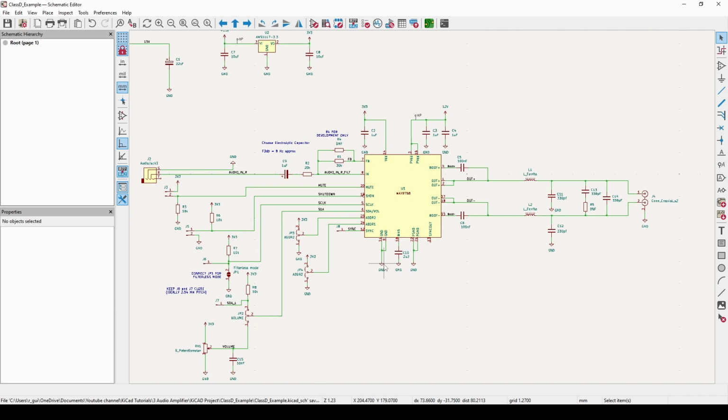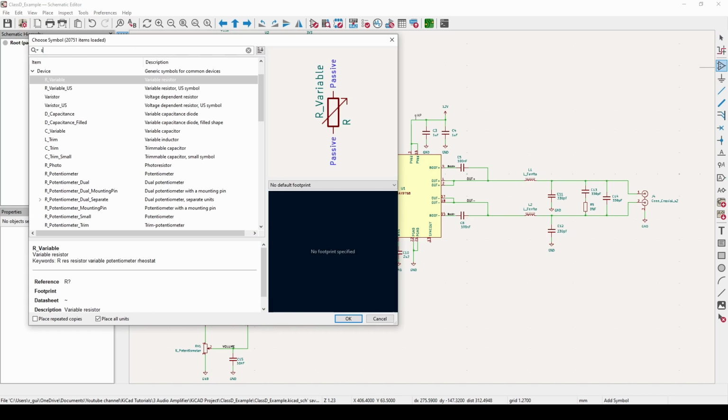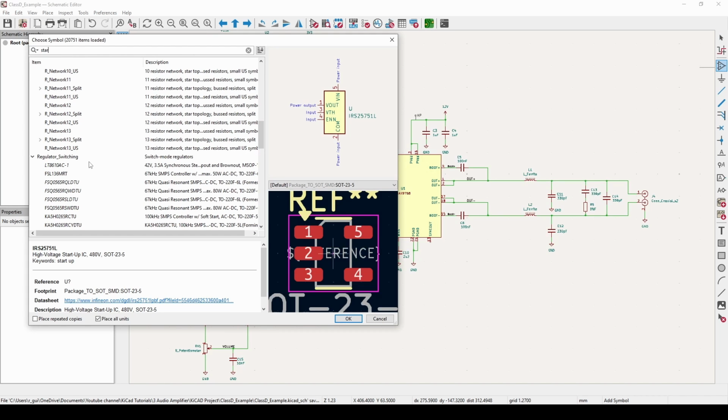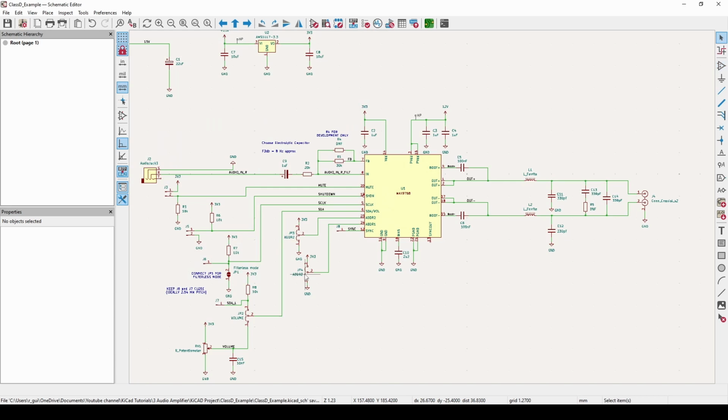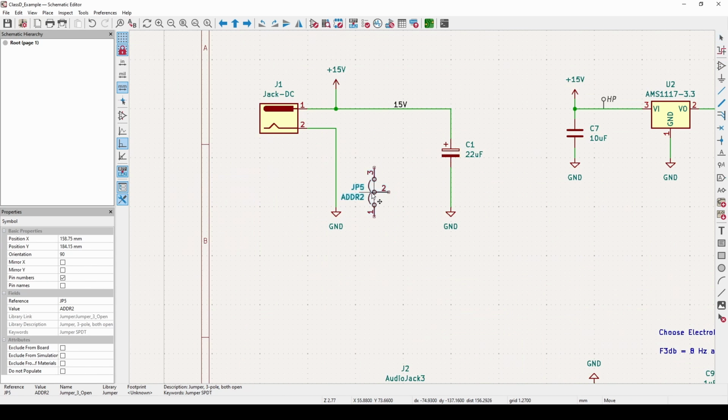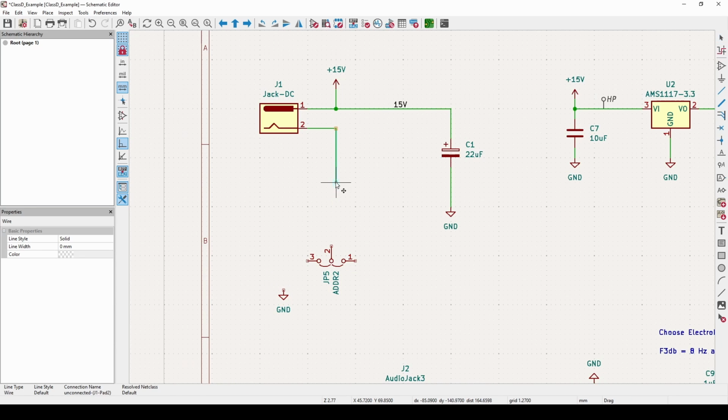So let's now quickly sort out the ground connection. What I need is a star node first of all, which hopefully I can find on here somewhere. I don't think there is a star connection. So what I'm going to do is just use a 3-pin jumper pad, basically connect that up to this node over here. One of my nodes on this line is going to be the normal ground.